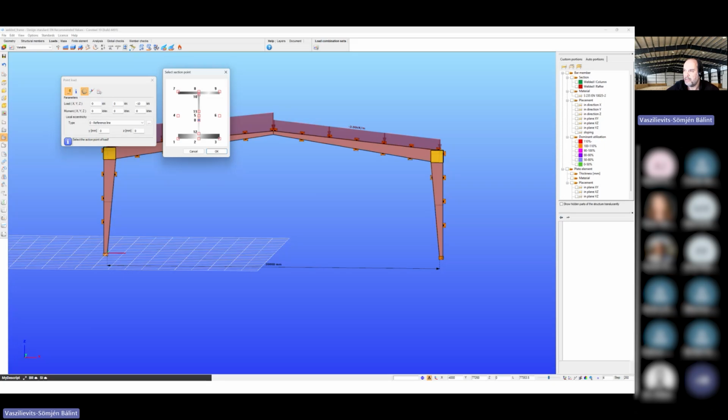That would also mean that with that feature implemented, there will not be any problem with the positive or negative type of sway, or any other sway. Consteel will always select the appropriate sway imperfection from the available elastic buckling mode shapes, and will always scale them accordingly to the worst direction. So that would be something hopefully coming soon, and that will simplify the work. Up to now, what you need to do is really make sure that you always apply it in the right direction.